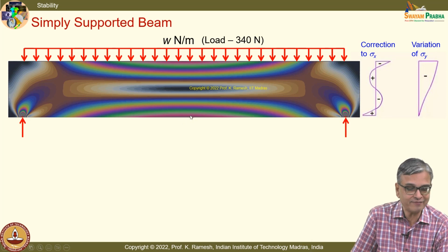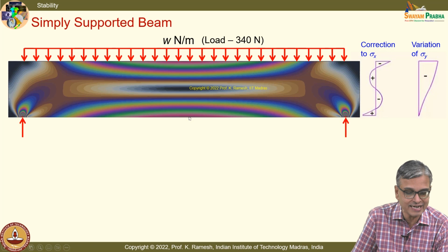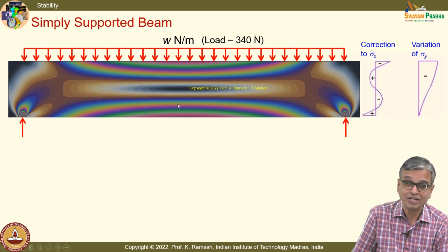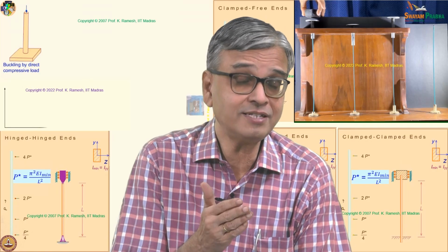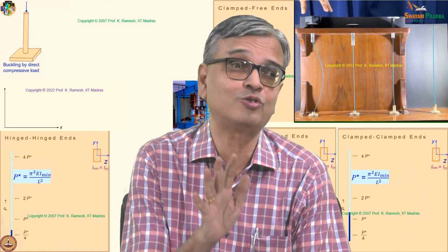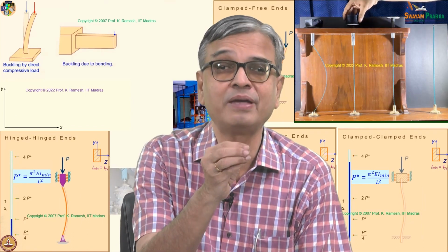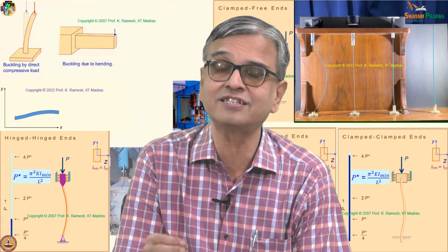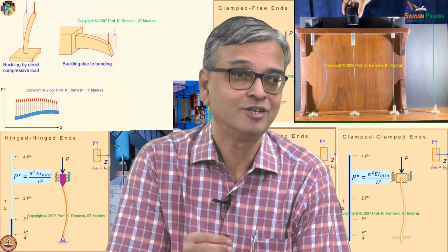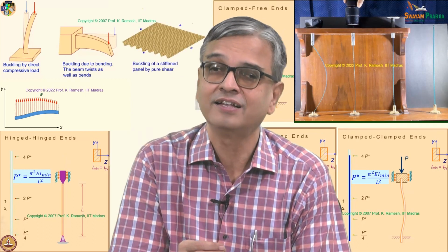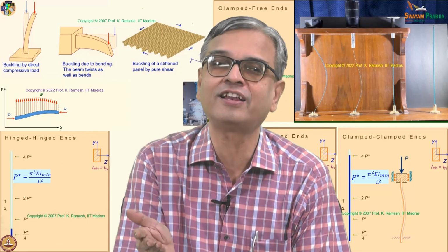The fringes are well developed here, and not fully developed there. You see beyond this red some slight shade of color coming out. The width is broader here, the width is shorter there. Okay, you have to be sensitive. The experiments reveal truth. Please understand. You may make certain simplifications for the purpose of your analysis. You may say curvature is linear. Experiment recognizes this as non-linear.